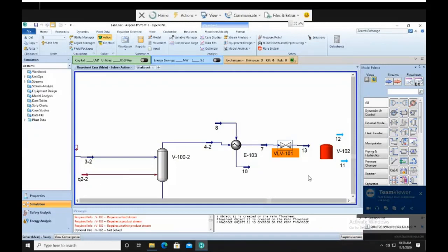When you work in industry, you have to evaluate which one is worth it: to increase the pressure by installing a compressor so that you can store your liquid at 25, or to store it at 8 bar, meaning that your whole design has to be at 8 bar, no compressors, but you are going to use utility to heat this one up to 10 degrees Celsius all the way.